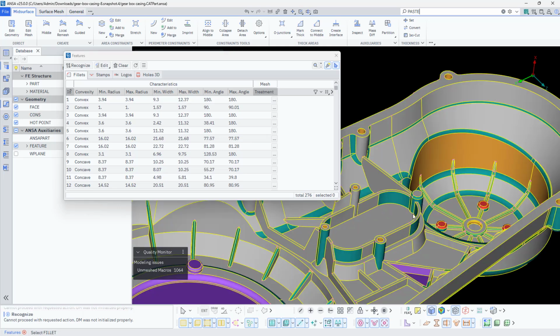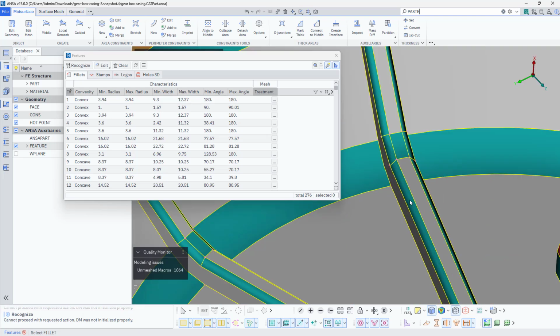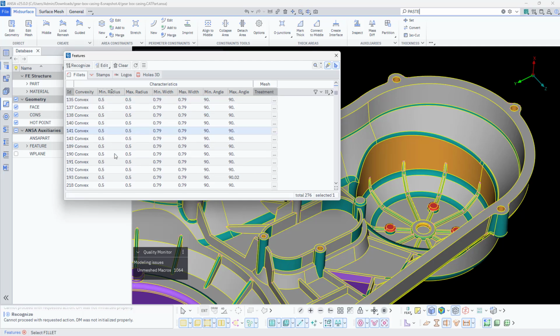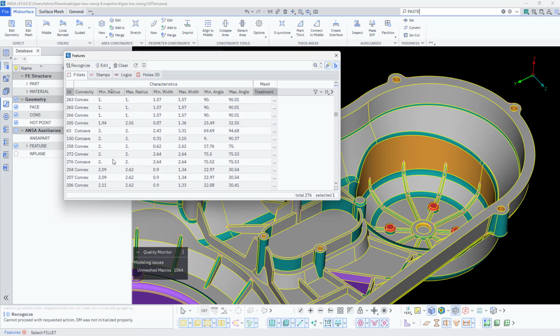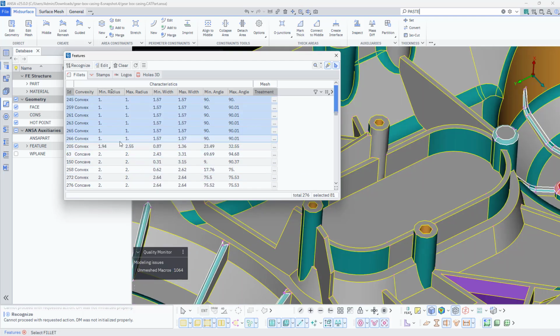Why we are doing it is, let's say you're going to mesh the model with a minimal mesh size, at that time you can check for the fillets. These are the fillets which have 0.5 to 1 mm fillet radius. If you're going to mesh it with a 5 mm or 4 mm mesh, these will simply create issues. So for that you can simply sharpen them.